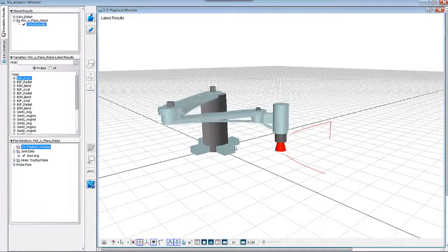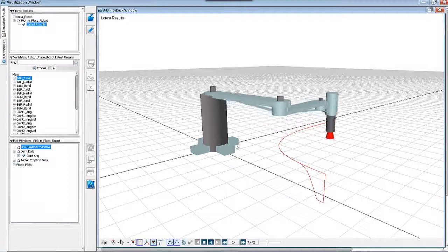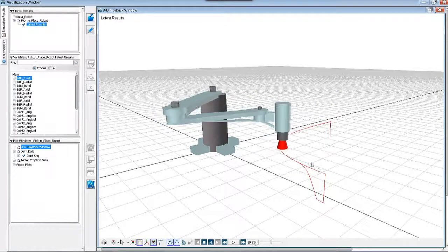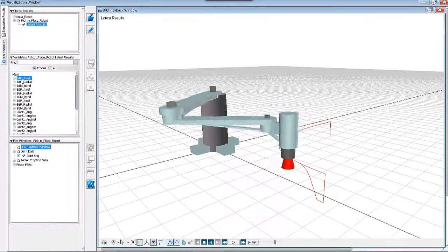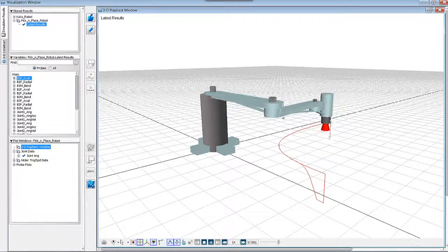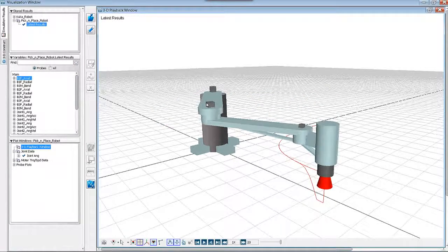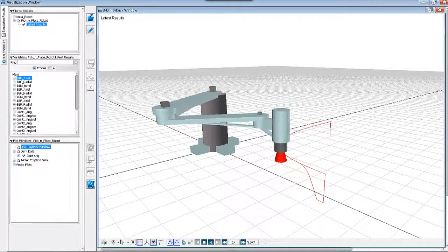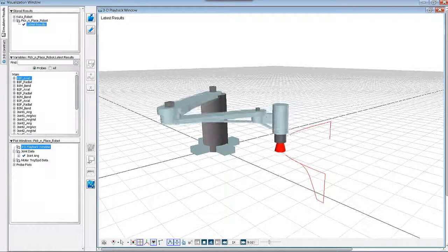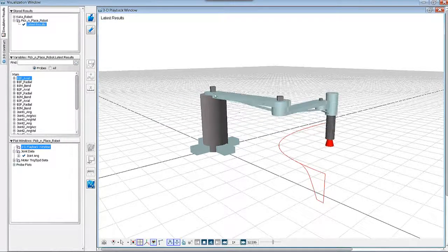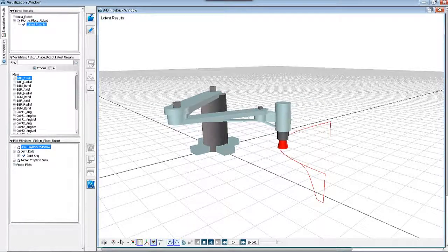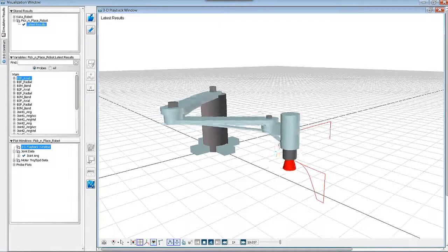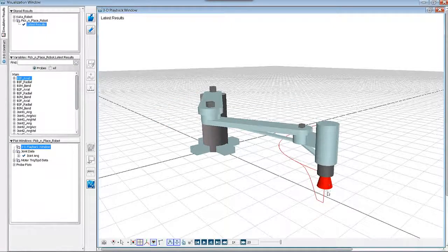So we can see that this pick and place robot is performing a fairly simple operation. The robot itself is following a desired trajectory of the end effector motion, and I can indicate visually what the different motors are going to be doing for each of the different joints. I've done this by these little blocks on the top of the joint connections here. As the motor articulates, you can see that the motor is spinning at a very high speed, and using a high gear ratio we can get the desired motion for the different links. There are 3 motors that result in the revolute motion of this mechanism, providing 3 degrees of freedom, plus a translational component that allows for the pick and place action at the end effector.